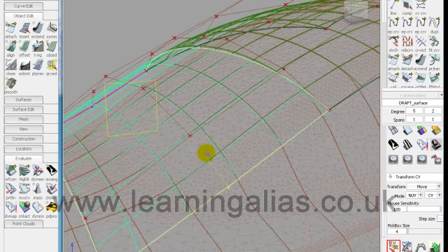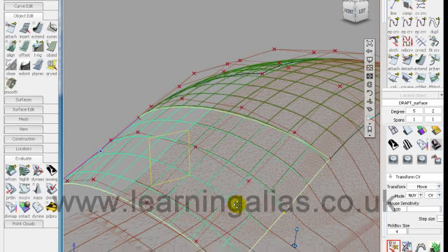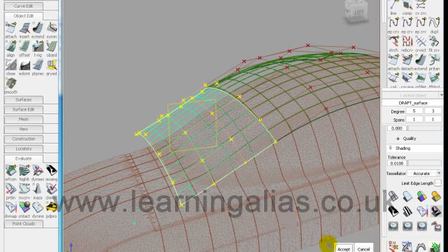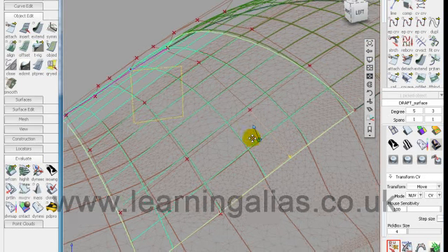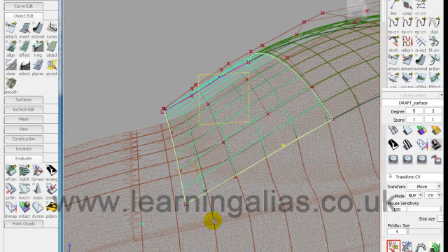See there, because we don't have enough CVs, we're not following the cross sections very accurately. So we go over here and we'll up that to degree 3, I think will do us. There. I'm purposely not using the deviation shader at the moment, just showing you that it can be done like this. And then it's too long, so I'm now going to use negative extend